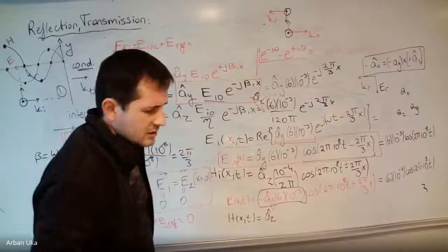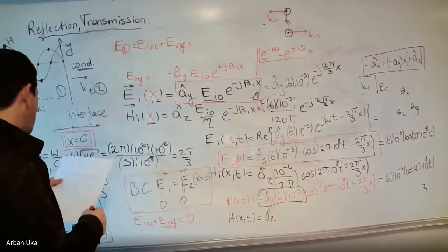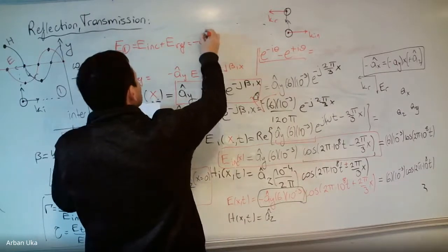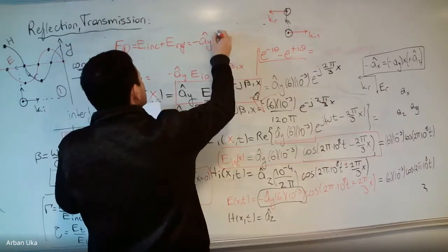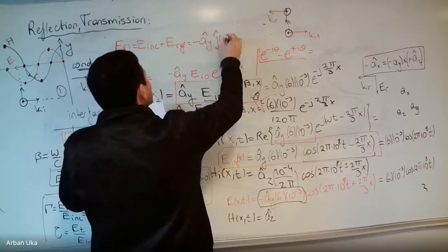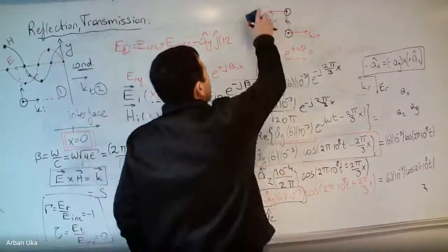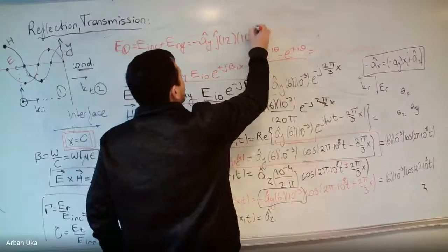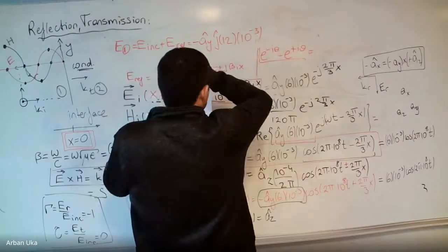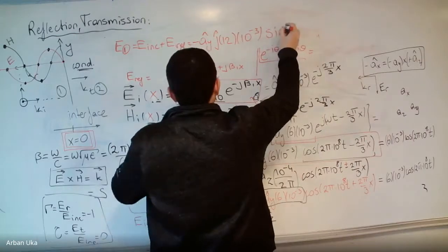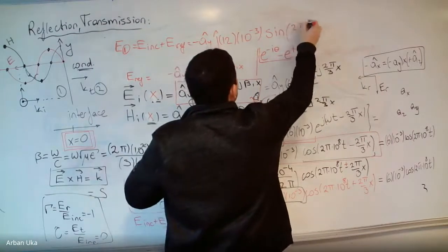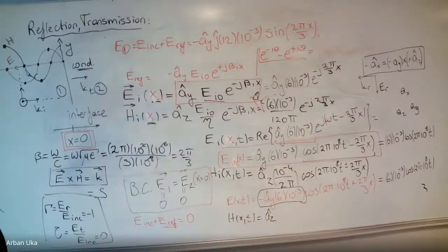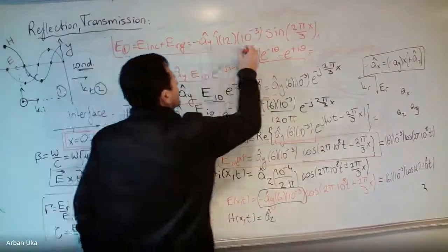Yes, so in here we should get the sine term. If we add these two together, we get the following: minus a_y, this is the negative sign, times j times 12 times 10 to the power minus 3 sine of 2 pi x over 3. So this is the beta x. Beta is 2 pi over 3. So this is the electric field in the...